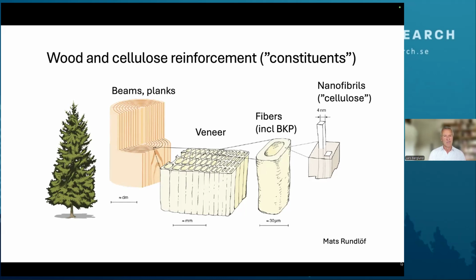We tend to distinguish between wood and plastics, but of course, wood is a polymer material, and the cell wall of this fiber is quite interesting. It has cellulose fibrils in a molecular mixture of lignin and hemicelluloses, but the cellulose fibril is really what we're utilizing in composites, because this fibril consists of extended chain cellulose molecules.